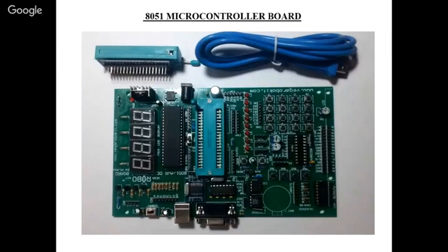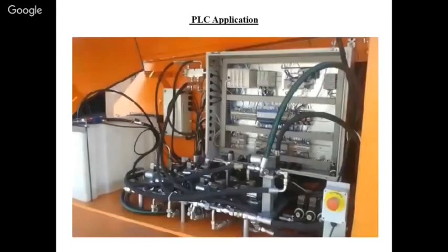The second thing is the burner and programmer issue, because the microcontroller board requires a burner and programmer, and you have to solder things or purchase the board. You also have to install software for interfacing the computer with that board. For hex file generation you need the Keil compiler, and then another programmer to upload the hex file to the microcontroller. So it is a long process, and that is why Arduino exists.